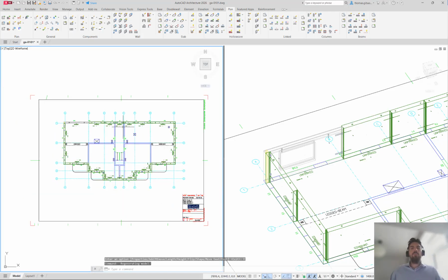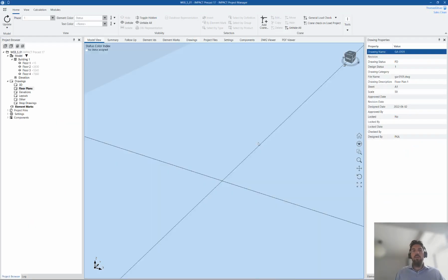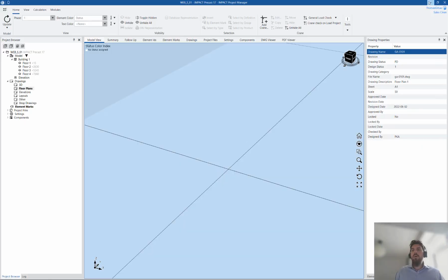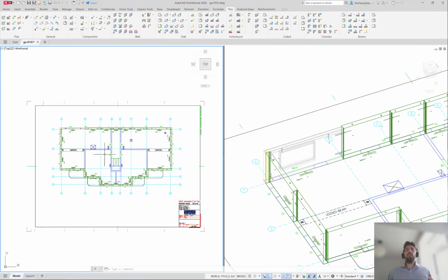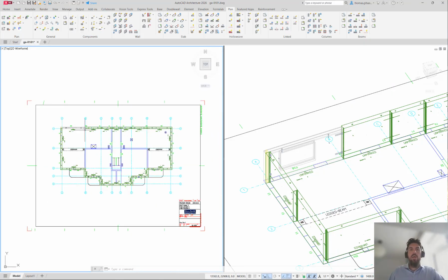So what I'm going to do now is, of course, impact, and maybe I didn't mention that before, but impact has 3 stages where we work. We draw, we edit, and then we save. If we do not save, then we do not get the data into the database. Until we save, the data is flexible. The data exists only in this drawing in AutoCAD.